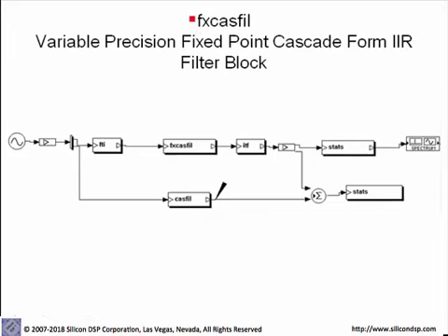So here we have a block called FIL, which implements a Cascade filter using fixed point arithmetic with variable precision, where you can specify the word lengths, the fractional part, and the round off after accumulations. And this block actually implements the fixed point Cascade sections, and you can directly map this filter to either a DSP implementation given the DSP architecture for fixed point DSP, or directly to RTL and eventually to an ASIC, or for example an FPGA.